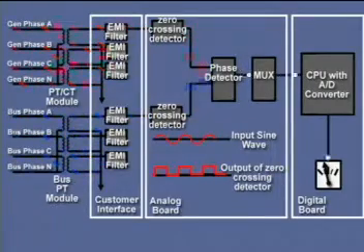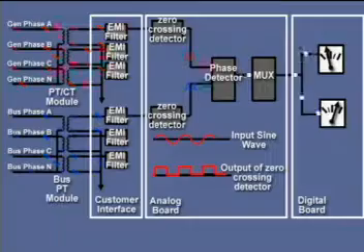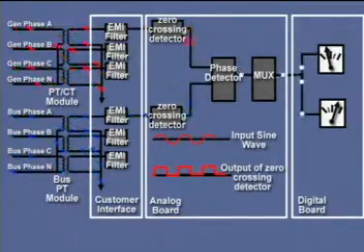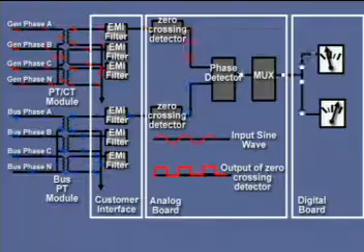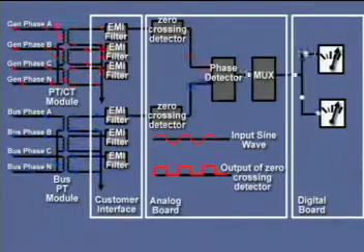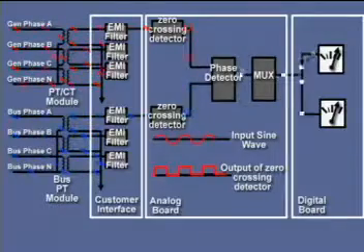The bus PT signal is used by the PCS as a voltage reference for synchronization. PCS uses the phase detector on the analog board to check this signal against the PTCT module's voltage signal. It then verifies the genset is properly phased to the main bus before allowing the circuit breaker connecting the genset to the bus to close.